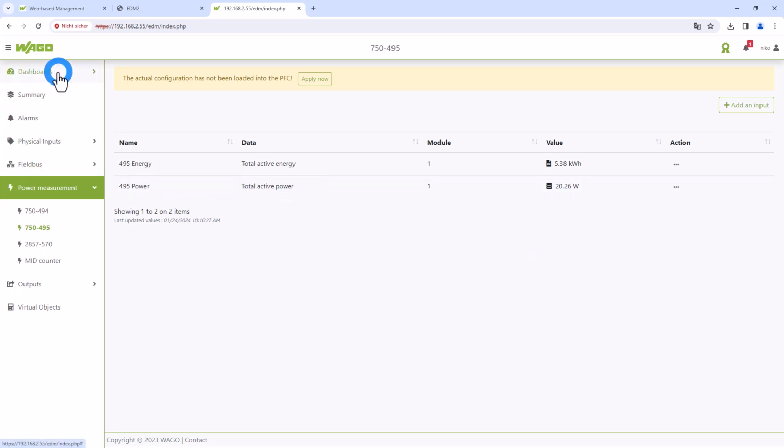The first target of this add-on is to visualize, but the second one is also, if you want to configure a few things, maybe you create a chart and say, oh, scaling is not so good. Then you can just change the scaling here, and at the end apply the changings, and then it's downloaded to the database, because the application and visualization work with the same local database. But be careful, the complete commissioning I recommend to do in the application and use this as a visualization tool. That's it. That was in a few minutes the application energy data management.